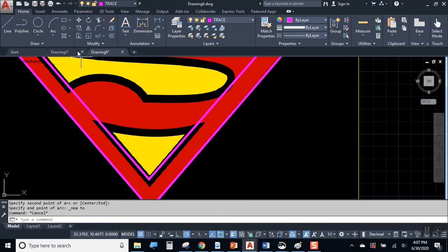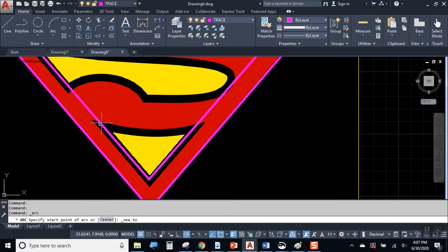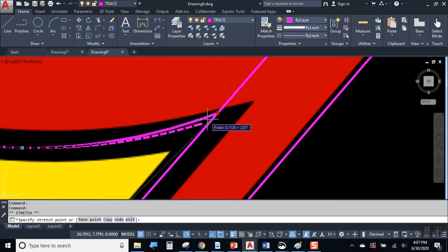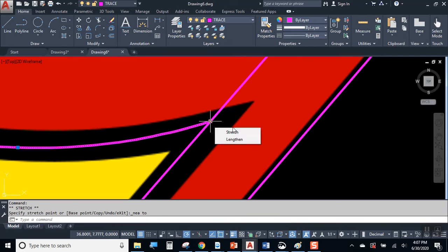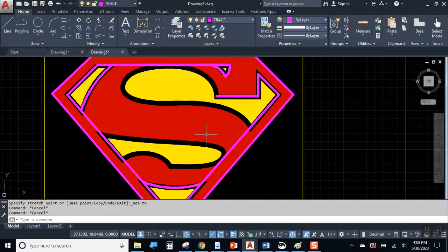So where you can use lines, and where you need arcs, use the 3-point arc. The snap to nearest is kind of nice when you're doing stuff like this because we're not trying to be so accurate. We're not looking for the tangencies and the perpendicularity like we were when we were doing a technical drawing. This is more like graphic arts, right?